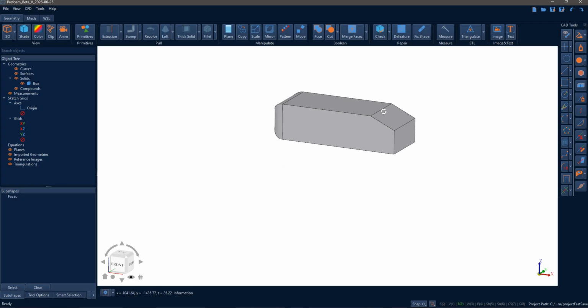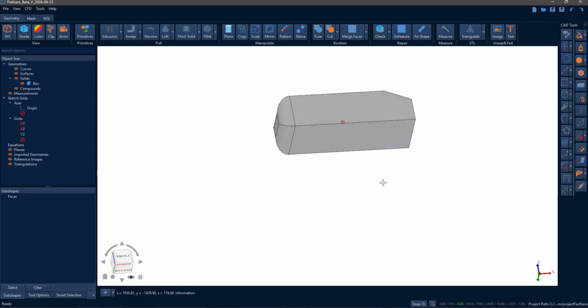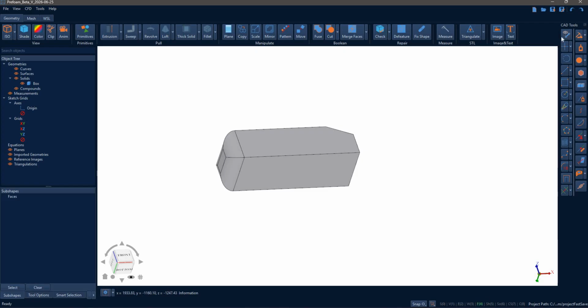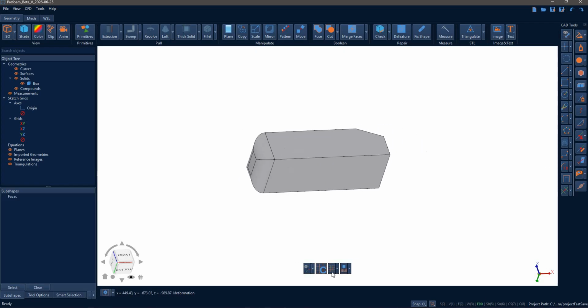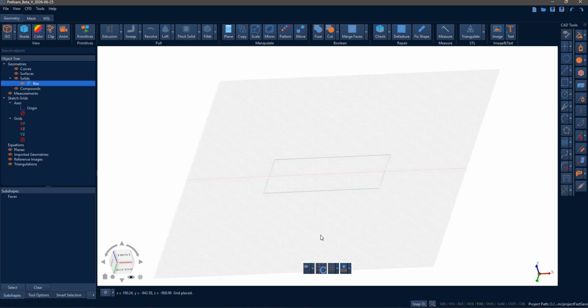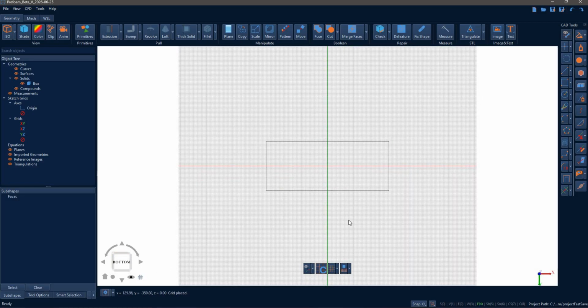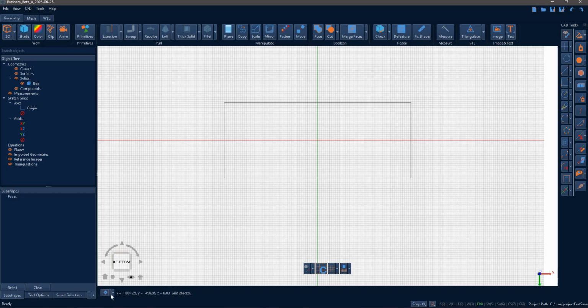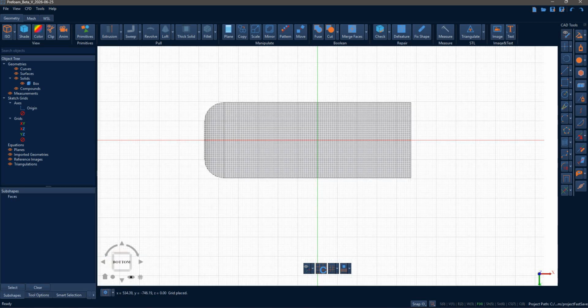And hereafter we need the legs, obviously. So for this I will activate the grid tools, then grid on surface, enable face selection, and I will apply a grid here. So by selecting the body and then hitting this button, you will project the lines of these right to the grid.